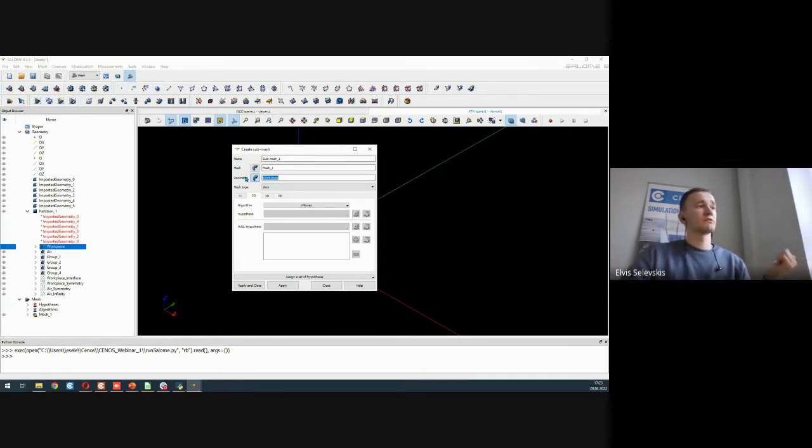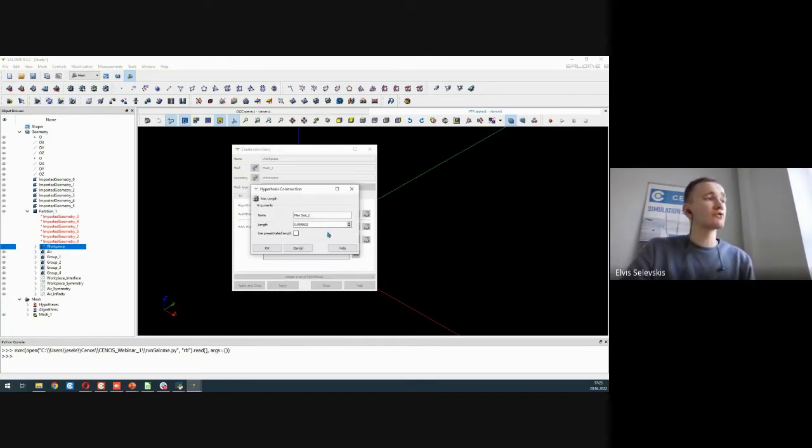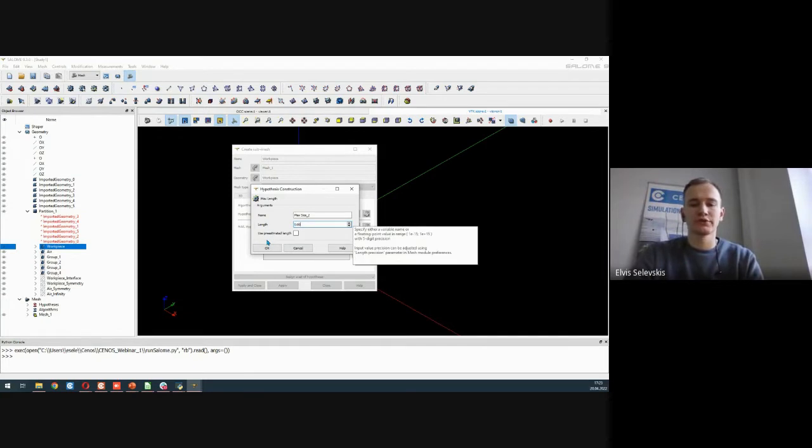So I click on it. I also love to rename the submesh in its name. And then once again, we go to assign set of hypotheses to the automatic triangulation. And right now, as I said previously, we have to reduce this max size value to something smaller. So here it's 0.03, that's in meters. So let's go with 0.005. Let's see what happens.